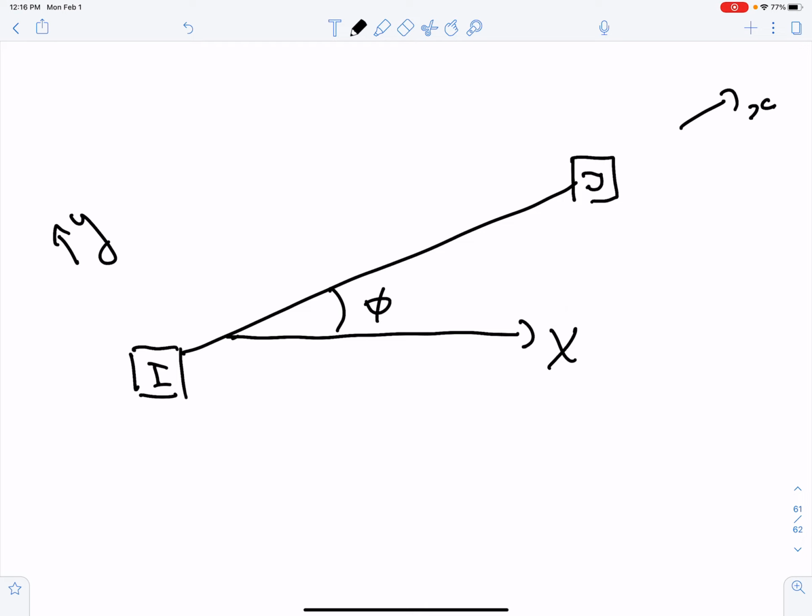Just like in the global coordinate system, node i can displace in the little x direction by an amount that I call delta 1 prime. Note the difference from delta 1. Here's the prime notation: everything that's referred to a local coordinate system will be denoted by primes. There could be the corresponding force F1 prime at node i.